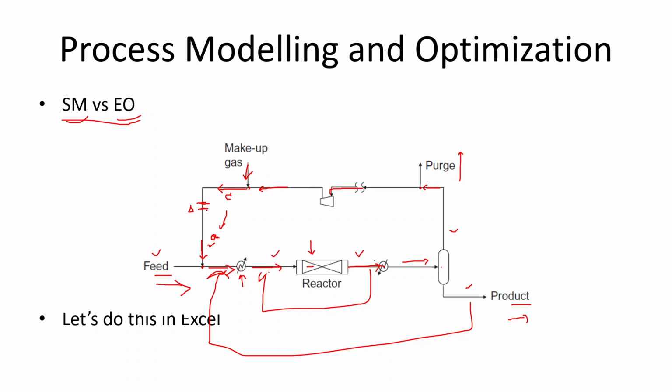So it will try to minimize this error in such a way that it converges the whole flowsheet at once. Okay, they also use the same kind of optimization solver like Newton, SQP, and Broyden and whatnot. So it's just a matter of how they approach this. The solver can be the same, but the calculation is done either sequentially block by block, or they take all the equations at once and solve them simultaneously.